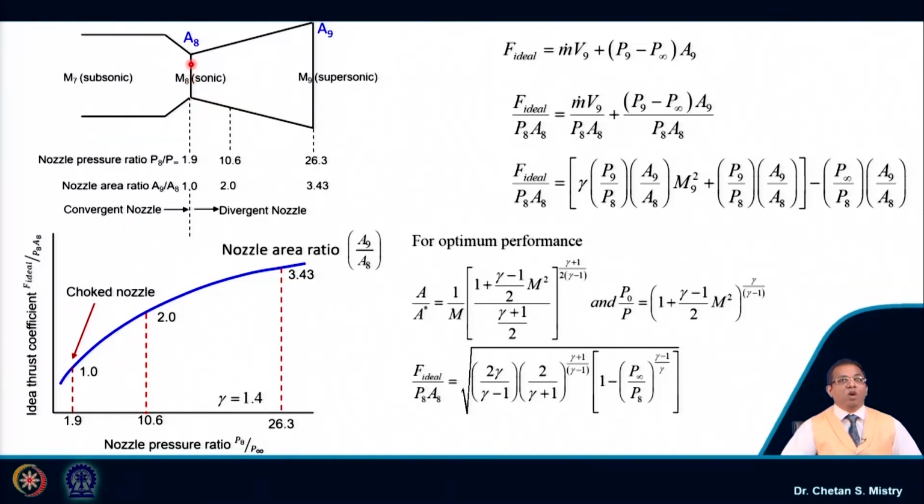For that pressure ratio, I have the constraint of the sonic condition. So, I cannot increase the Mach number further, but still if I am looking for a very high Mach number, then I need to go with a convergent-divergent configuration. Here this represents my converging passage, followed by the throat, where I will have my M equal to 1 condition, and further acceleration towards the supersonic Mach number can be done by using this diverging passage. The area at the exit of my diverging passage is what we represent as A9.